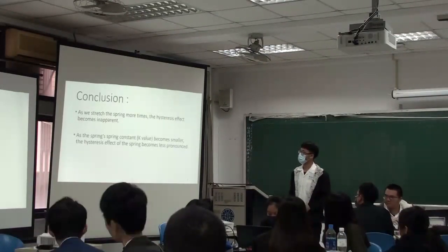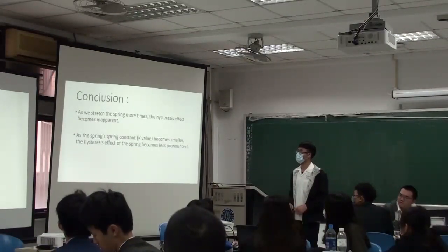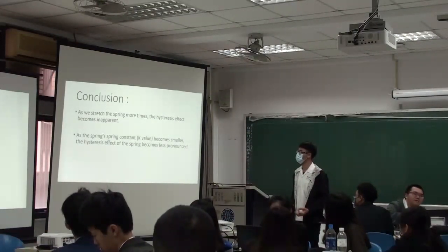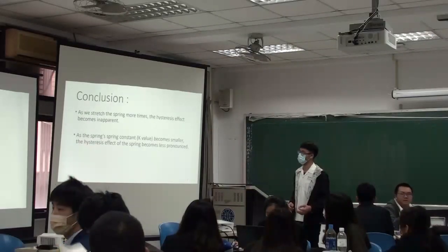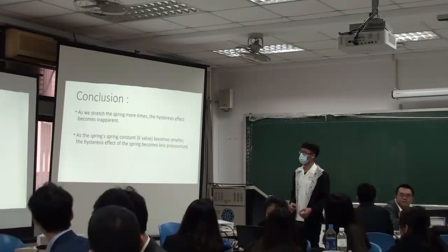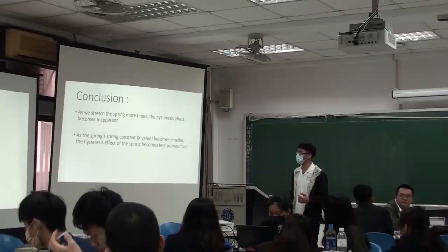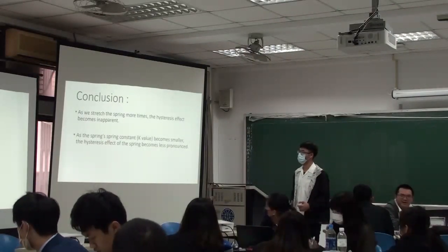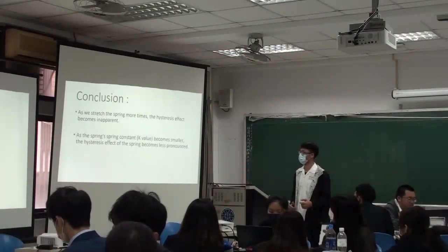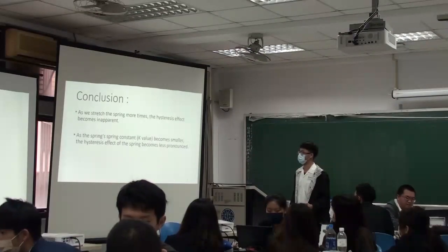Yes. And this is our conclusion. As we stretch the spring more times, the hysteresis effect becomes inapparent. And second, as the spring constant value becomes smaller, the hysteresis effect of the spring becomes pronounced.